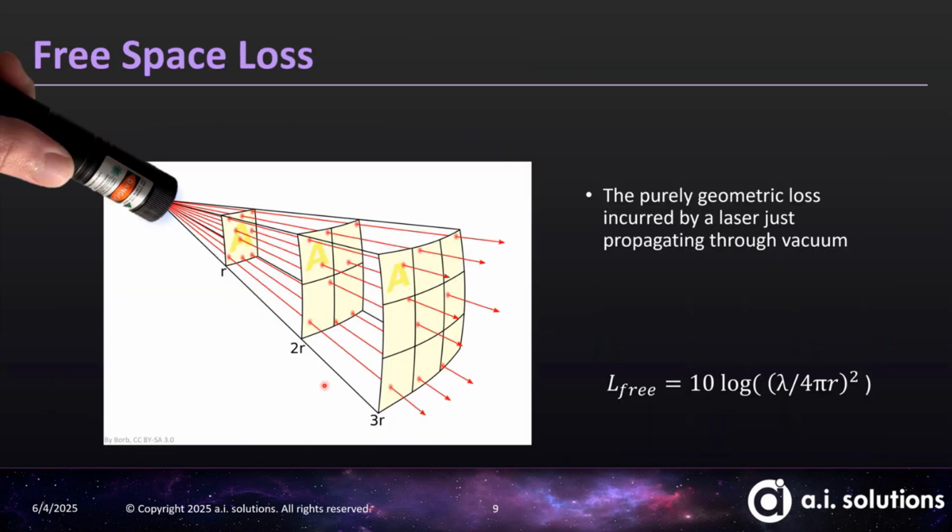In terms of losses, we are always going to have free space loss, just like we do for radio communications. It's just a fact of math and physics that you're creating a signal, and that signal essentially gets projected along the surface of a sphere, and you get losses just based on that happening. So you're always going to have this to deal with, no matter your environment.